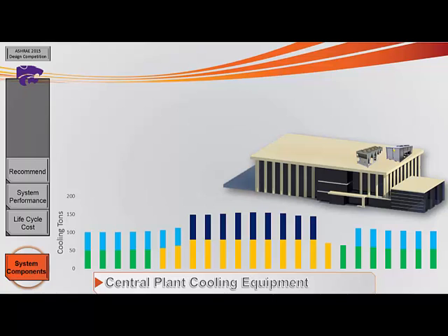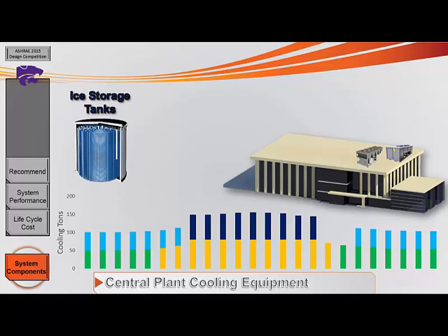Because the building is charged at a higher peak electrical utility rate during the day, an ice storage system will be used to reduce energy costs. The ice storage hourly output is shown below in dark blue. This system utilizes the glycol chiller to create ice at night when utility rates are low, and discharges this cooling energy during the day when utility rates are at their peak. This concept is called peak shaving.